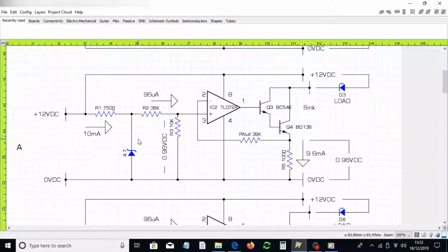You can get bubbles within the chemistry which affect the voltage, and per year you get a slow dissipation of voltage, slow drop of voltage, and I think it was 50 or 60 microvolts on a Weston cell. So you'd have to send your instrument off to be effectively recalibrated periodically. But all in all, quite a disadvantage.